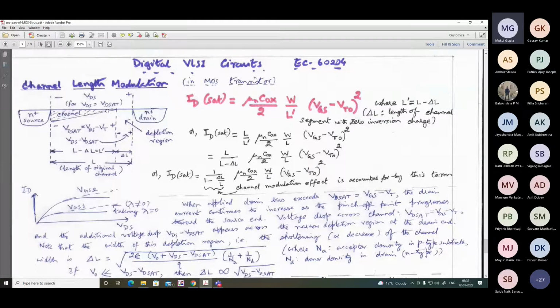So the channel width becomes constricted as you proceed towards the drain. When there is current flow, remember that on the drain end side, the channel width is shorter compared to that of the source end. Now, let us assume that VGS is fixed, but gradually you are increasing the drain potential with respect to source. Then what happens?